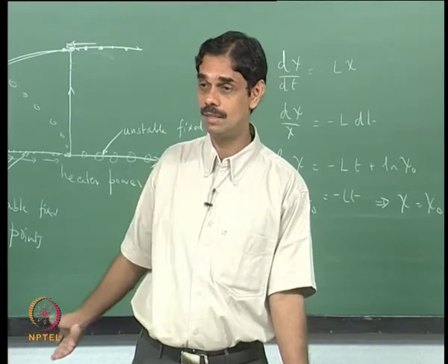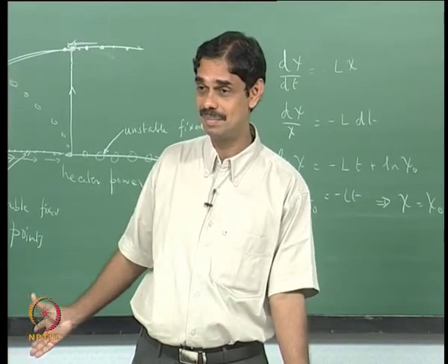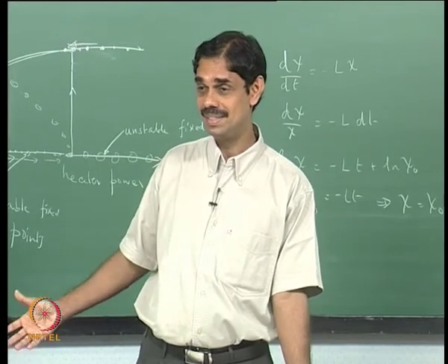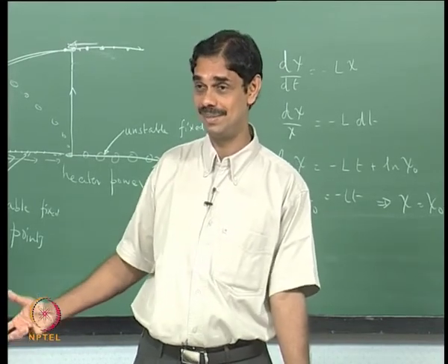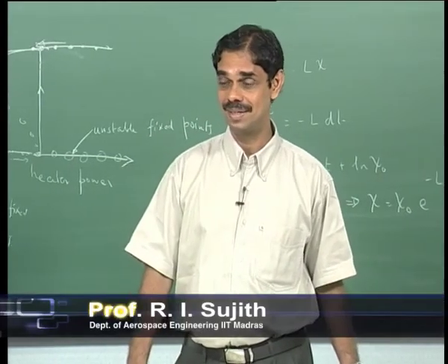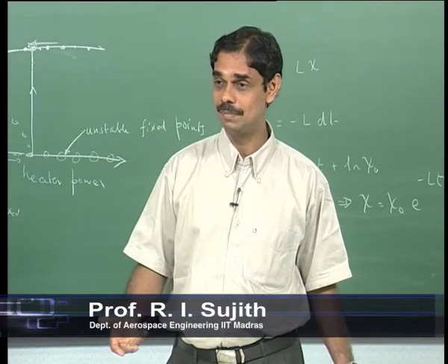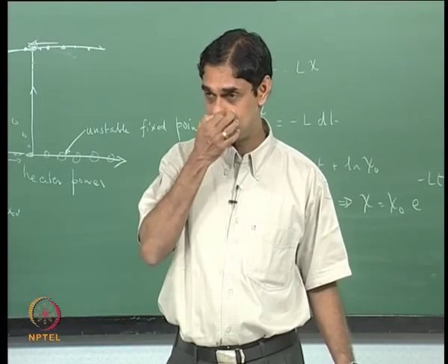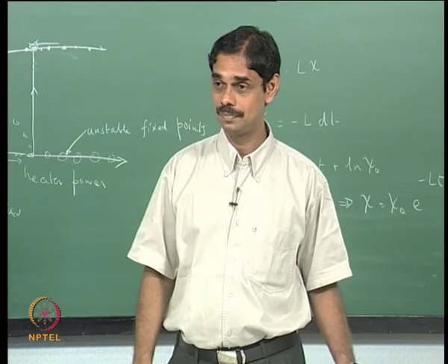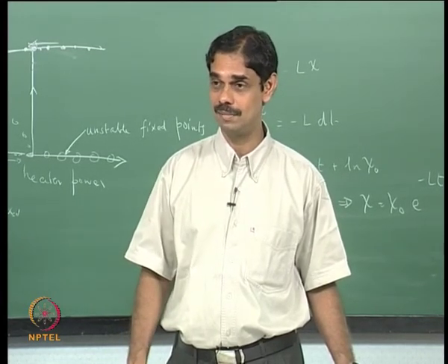In theory, in the correlation what we used is heat taken by the gas, but the experimentalists can't quite measure it. I mean, in principle it is possible, but very expensive, you need to use some laser induced fluorescence or something. I won't even dream of doing those things. So it's much simpler to plot input power. In dynamical systems you can plot anything you want as the bifurcation parameter as long as it affects the system. That is the good thing about that machinery.